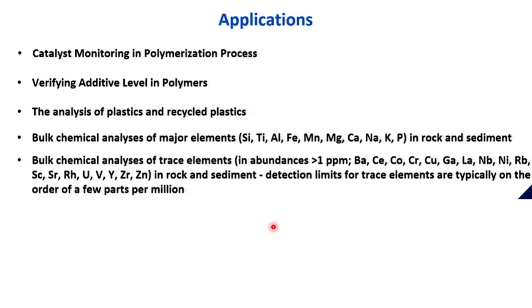So XRF has a very wide application area. For example, catalyst monitoring in polymerization process. Whenever a catalyst is catalyzing a reaction, after that you can check how much catalyst remained in your material, or how the kinetics is going on during the reaction.